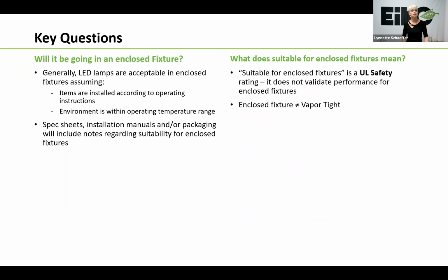Another question is, will the LED replacement be going in an enclosed fixture? Generally, LED lamps are acceptable in enclosed fixtures, assuming the product is installed according to the operating instructions, and the environment is within the operating temperature range. So when you're specifying a lamp, don't just think about what the temperature is today. Think about what the temperature is going to be on the hottest day of the year, and make sure that you're recommending the lamp that's appropriate for that application.